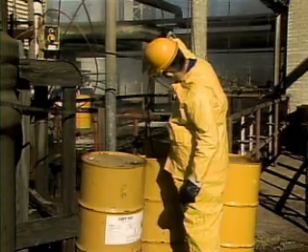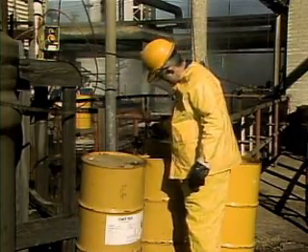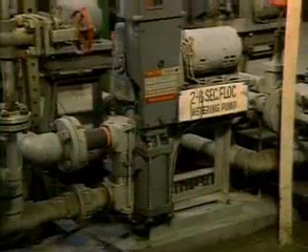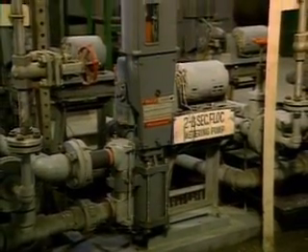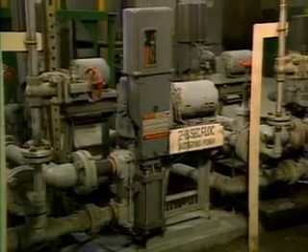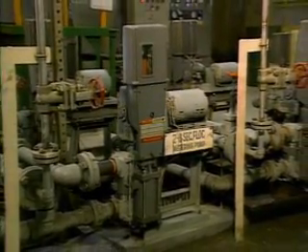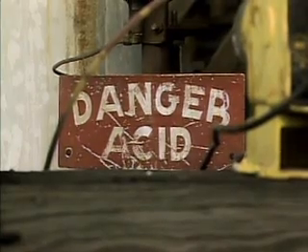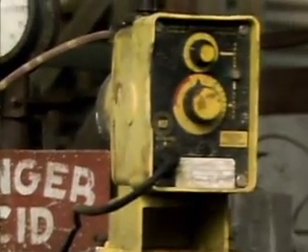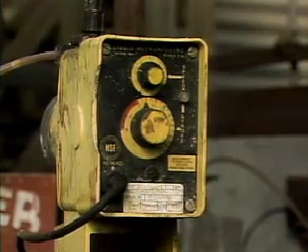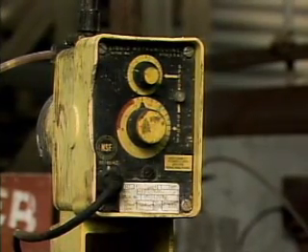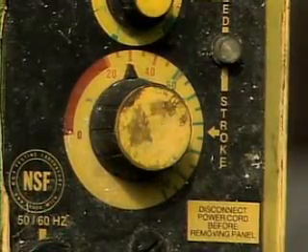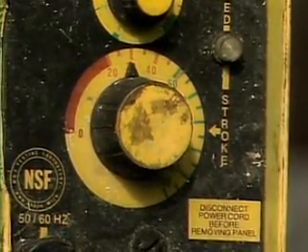You should always be aware of their specific hazards, and you should follow your company's procedures when you handle any chemical. The precautions you need to take may depend on how the chemicals are added. For example, some chemicals can be added so that there's no contact with personnel. Chemicals such as acids are added using chemical injection pumps like this one. On this pump, the amount of chemicals added can be controlled by adjusting the stroke of the pump. That's done by turning this knob on the pump's controller.